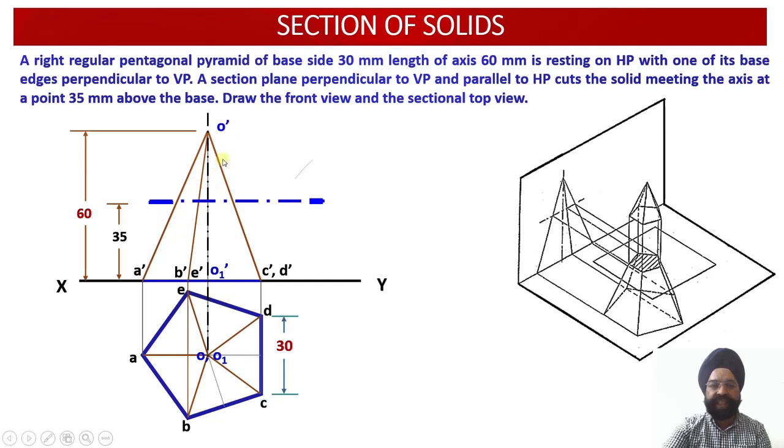And after darkening this, now I have come to know that this portion, that is a shorter pentagonal pyramid, was obtained. So this has been discarded. It has been thrown out. And then I am left with the frustum of the pentagonal pyramid. So these are the edges which are left with me. Just see, this is left with me, this is left with me, and this is also left with me. So now I am going to darken this. So we call this plane AHP, that is, the auxiliary horizontal plane, because it is parallel to the horizontal plane over there.